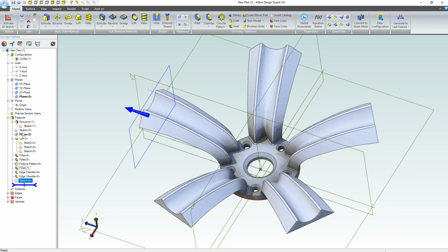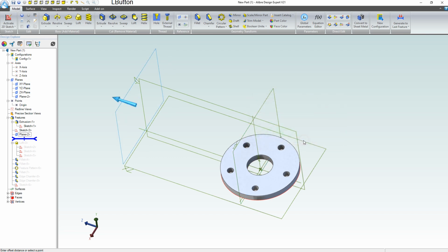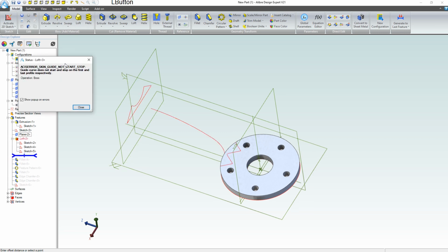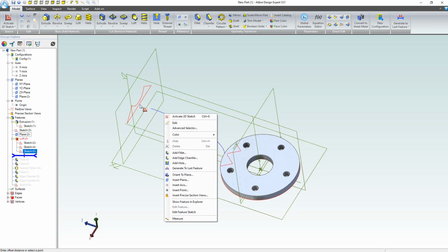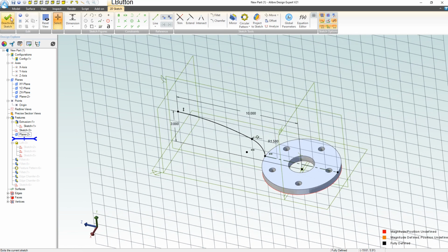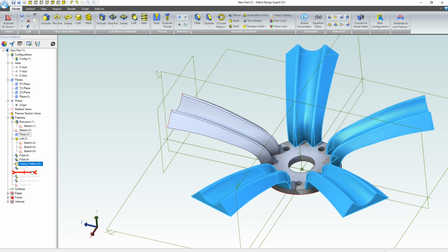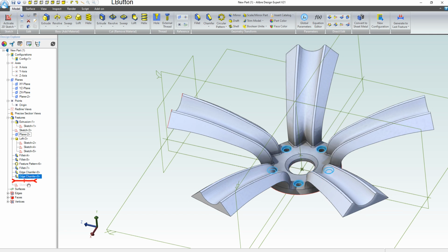That goes back to how I define my plane. So I should, in a parametric program, be able to take this out even further. Yeah. And now we should be able to rebuild, right? So I'll just drag my bar down. Well, maybe... Oh, so I've got a little guide curve error, and that makes sense because I did not constrain that guide curve to that sketch. I think there's a way to do it. I just need to figure out how. So let's ignore, might have to step through this one at a time. There we go. Looks like everything is rebuilding nicely.